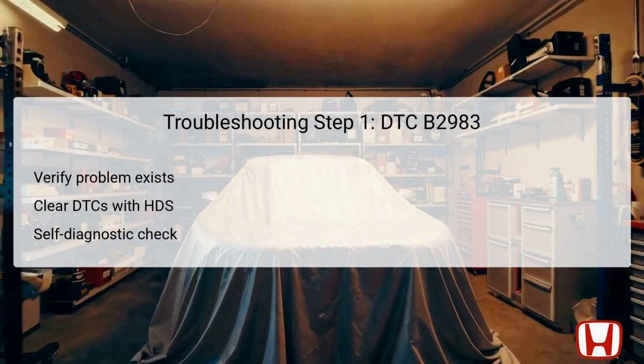If the code does not return, this could indicate an intermittent failure, which is often caused by loose connections or faulty wiring. At this stage, attention should be turned towards inspecting the motor circuit thoroughly for any signs of wear or damage.